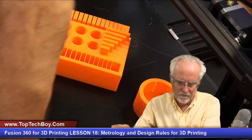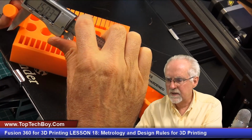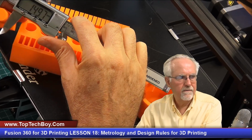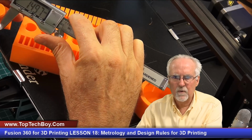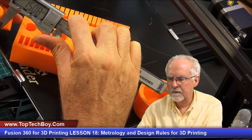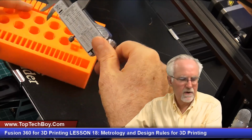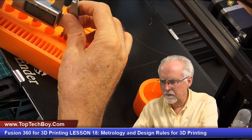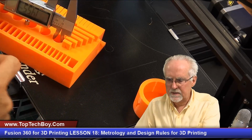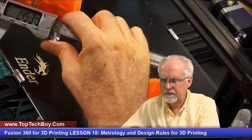What I'm going to do is come over here, and this was supposed to be 15 and it is round. And what it is coming in at is a little bit under that, 14.97. Okay, 14.97. So you see it's coming in a little bit less than that. And then let's check the hole here. And it is coming in even a little bit less than that. So you see, let me see if I can show you what I am doing here. This hole was supposed to be 15.